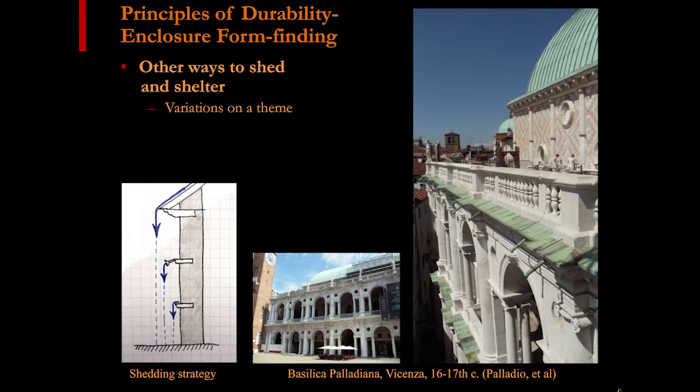These are essentially like a copper scupper, what the Italians call a doccione, which means big shower. And when it discharges all the water off this balcony, it does turn into a big shower. And the important point is it's clearing it all the way to the ground, and it's not just dumping it on the level below. So again, very thoughtful design and a variation on that same general theme and general idea.